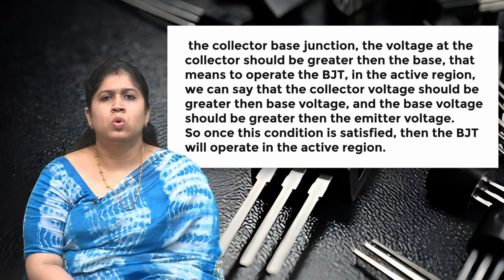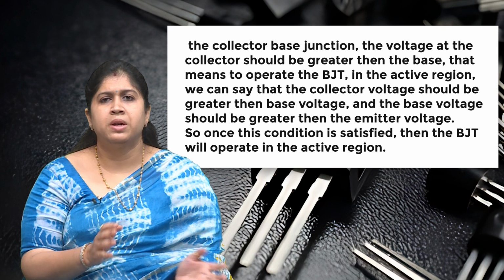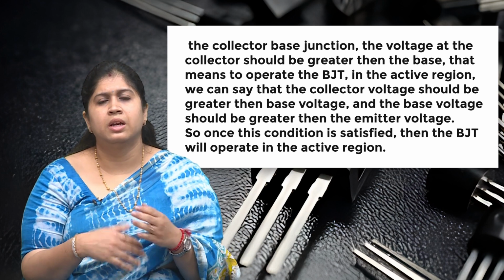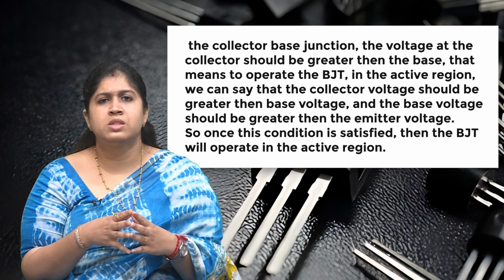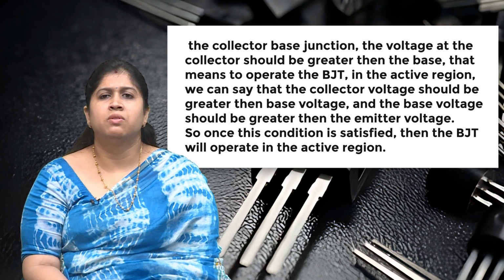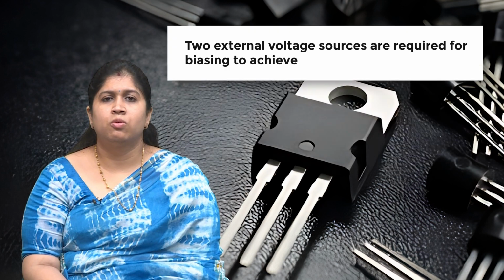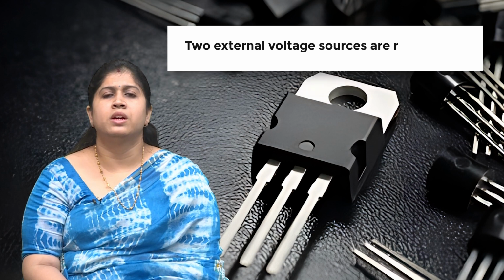That means to operate the BJT in the active region, the collector voltage should be greater than the base voltage and the base voltage should be greater than the emitter voltage. Once this condition is satisfied, the BJT will operate in the active region. Two external voltage sources are required for biasing to achieve it.